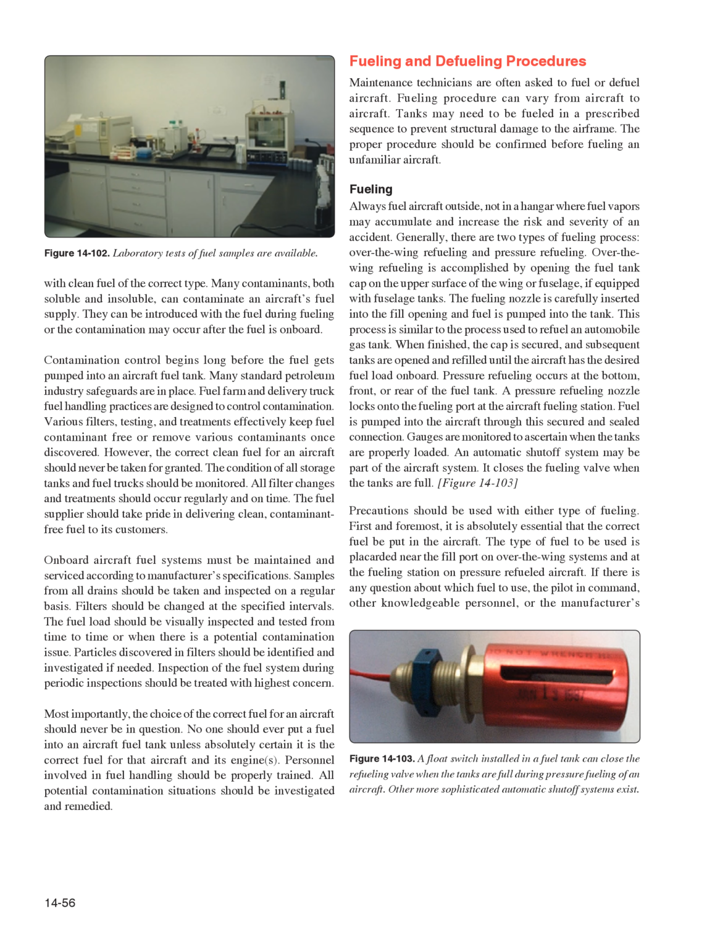However, the correct clean fuel for an aircraft should never be taken for granted. The condition of all storage tanks and fuel trucks should be monitored. All filter changes and treatments should occur regularly and on time. The fuel supplier should take pride in delivering clean, contaminant-free fuel to its customers.